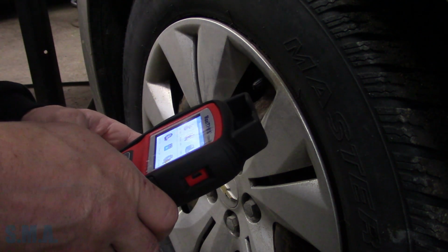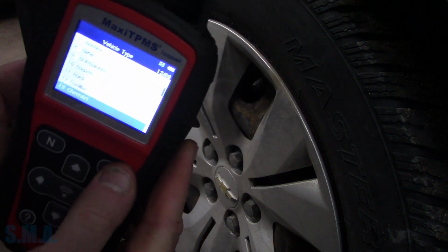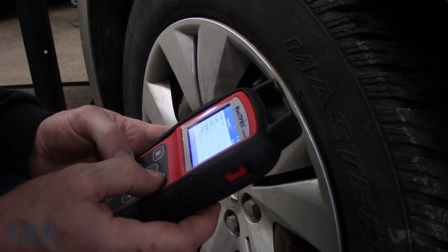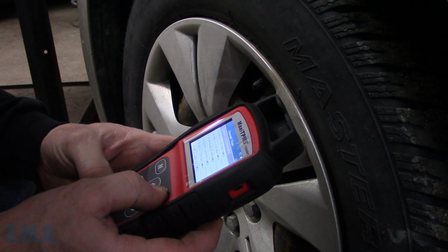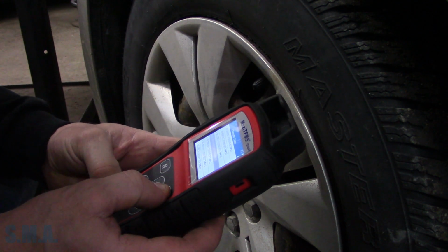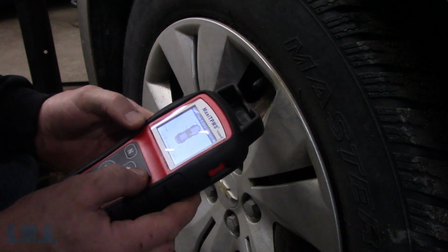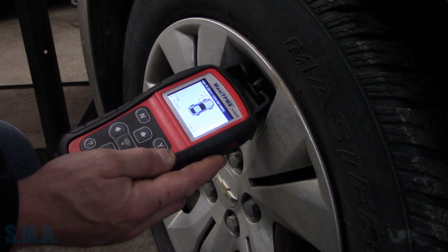We're going to go through. We're going to use our Autel. This is the TS508WF. That stands for Wi-Fi. It's a TPMS tool. We're going to select Chevy, then we'll get Cruze. We're going to go through and see which one of these sensors is bad. This is the 13 to 15. So we're going to go through and trigger every individual sensor, see which ones work, which ones don't.